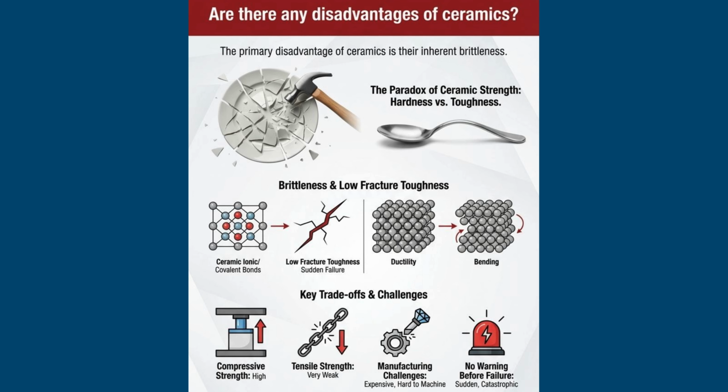Limitations of ceramic materials. Despite their many advantages, ceramics possess several limitations. Brittleness remains the most significant drawback, limiting their ability to withstand impact or tensile stress. Their low fracture toughness often necessitates reinforcement through composites or transformation toughening mechanisms. Machining ceramics is also difficult because of their hardness, often requiring diamond-based cutting tools or specialized processing methods. Furthermore, some advanced ceramics remain expensive due to energy-intensive manufacturing processes and strict purity requirements.